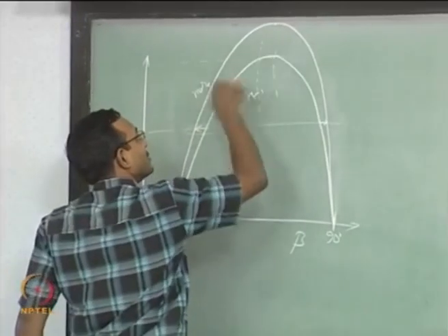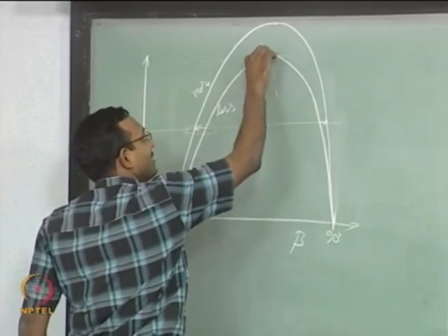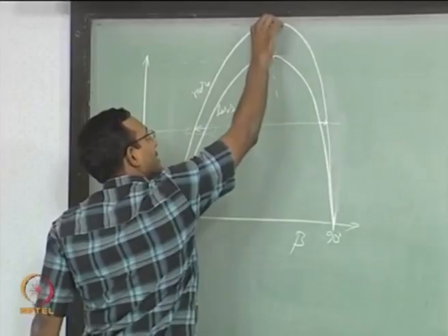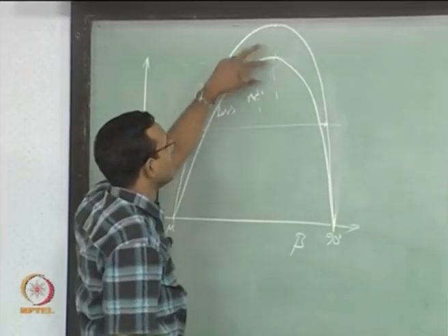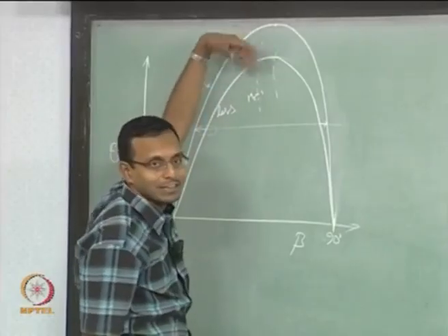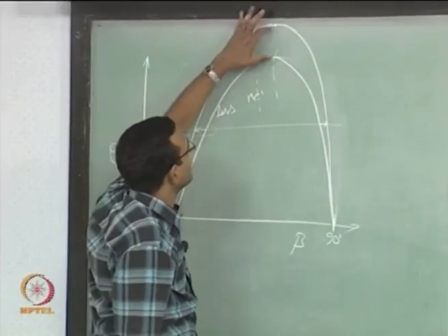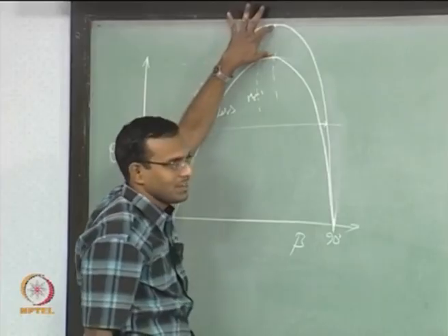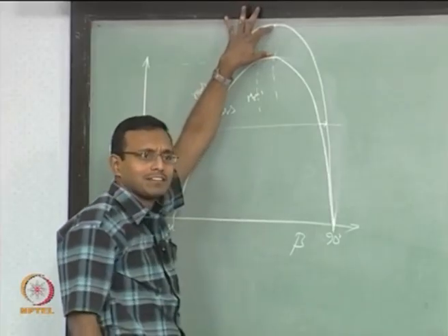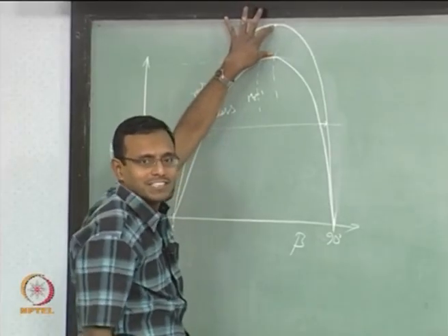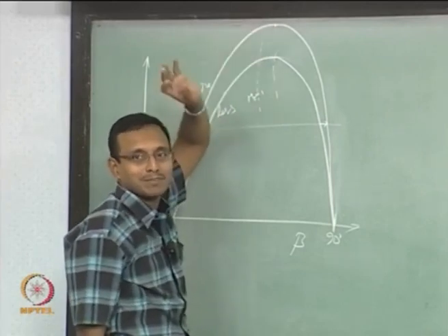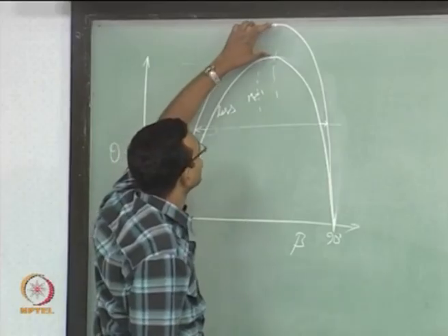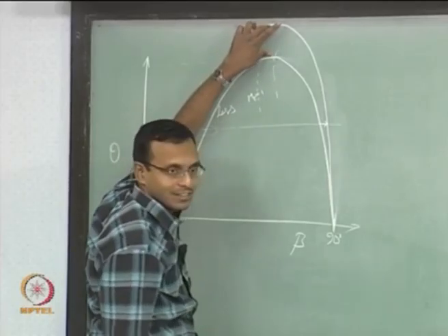The main thing I want to show in this plot is theta critical has now substantially increased, okay. It is not a very small number, if I increase my Mach number, this change will be really drastic, okay. You are going to see a huge change up here. Of course, when I go to very high Mach numbers like more than 10 or 15, this change may not be very high, it may saturate to some particular value, okay. That is the hypersonic limit, everything goes crazy there. So I am going to have something like this here, okay.